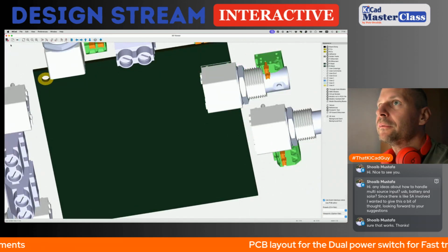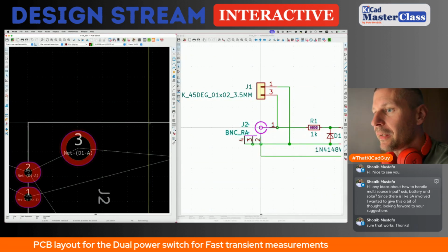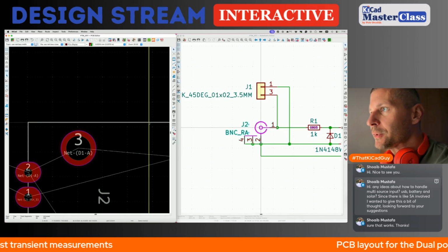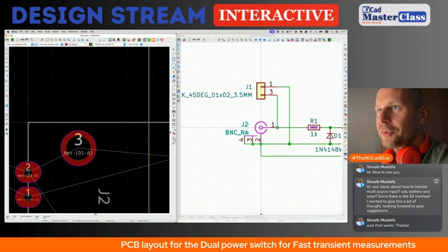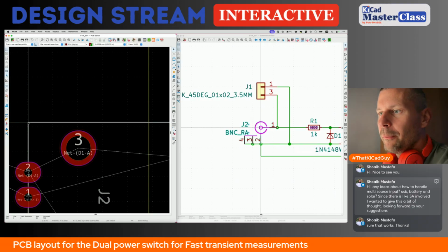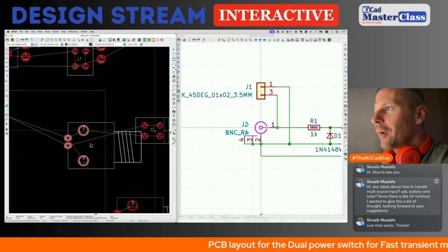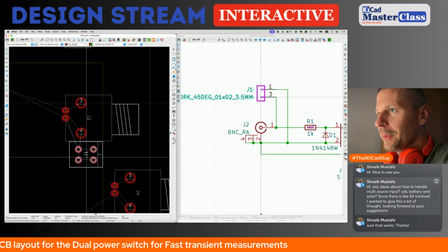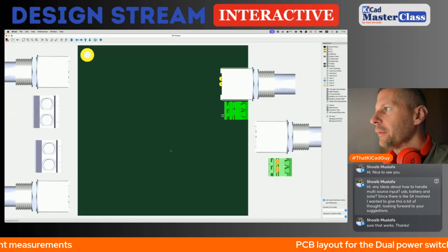Okay, so the position between the PCB edge, when I hit the space, I can zero the auxiliary scale on the bottom line of KiCad. So here is the 0, and roughly the opposite edge of the connector body is 12.27 or 12.3 millimeters. Okay. So this will be roughly the position of the BNC, and I will place the terminal like here.